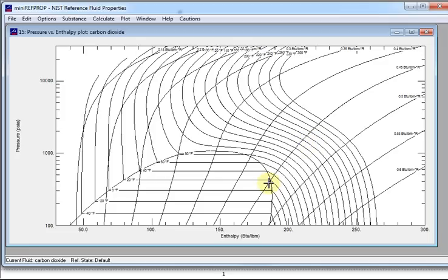I'm going to pause right now, and I'm going to hand you a printout of this diagram. And as a design engineer, you need to explore thinking about having two heat exchangers, a compressor, and an expansion valve. And you want to explore how high a pressure you push it to. Because you have the low pressure side. Let's say it's already dictated. The low pressure side is 300 psi. Because our evaporator, we want it to be absorbing heat at 0 degrees F.